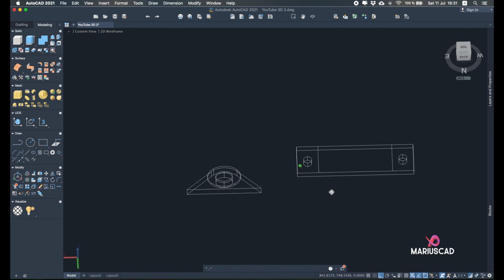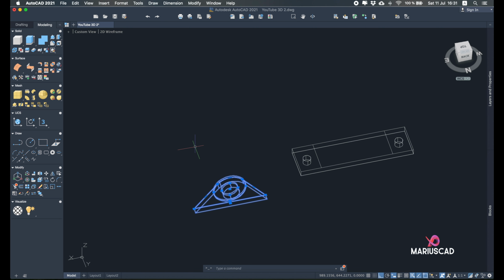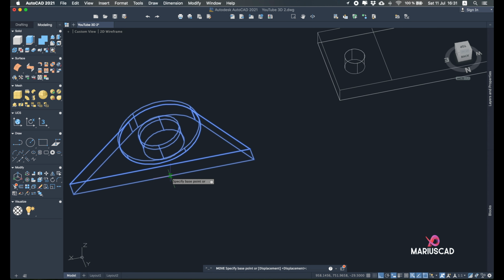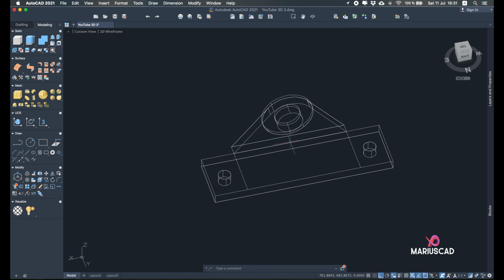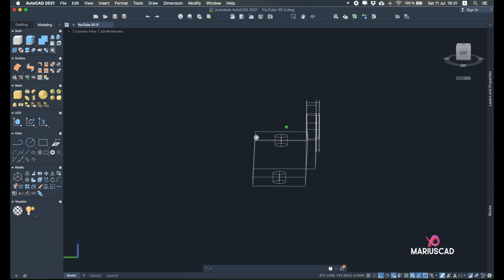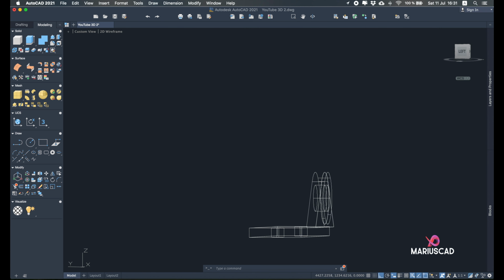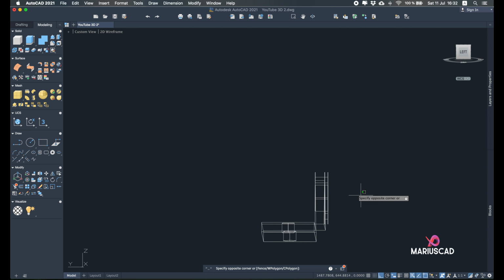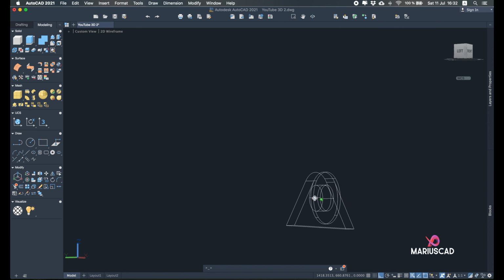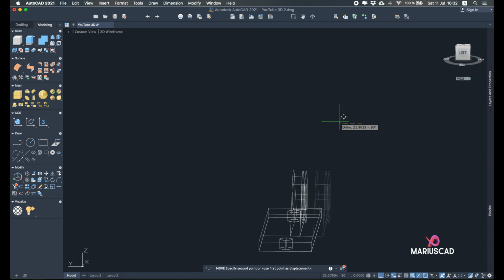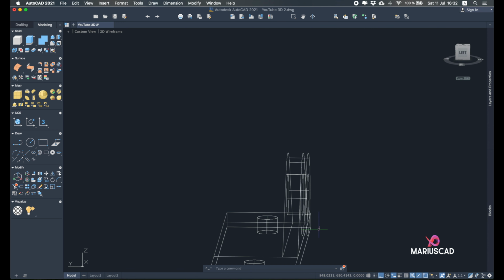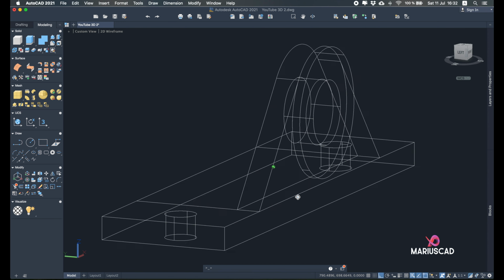And now, which is also very important, select the whole drawing, go with the move command and select the middle of this edge. You see this edge, go exactly on the middle and everything is wonderful. Now let's move the drawing again. So select just this part, you can see it. I will go not here, I will go just here, and I make sure that I select everything I need. Go with the move command and go exactly 9 units, if you remember. And now the edges are perfectly symmetrical here.